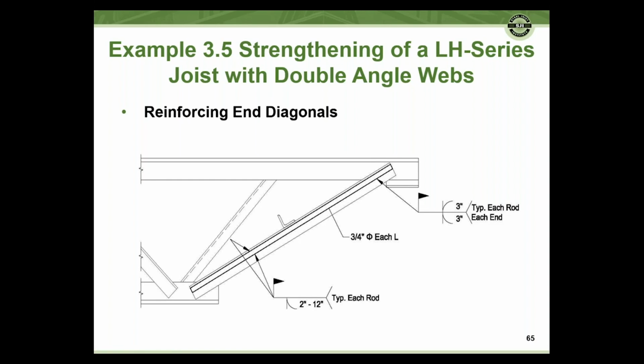I would mention, we checked just tension here. Be careful. If you have a joist that is under uplift conditions, you could have a compression load in here. So you're going to have to check this for compression as well.